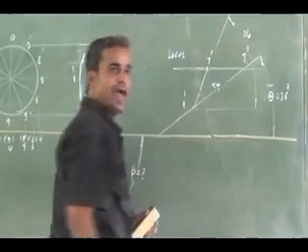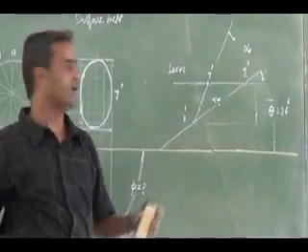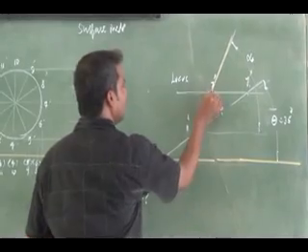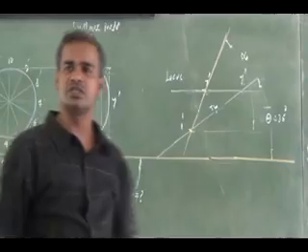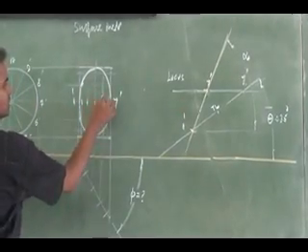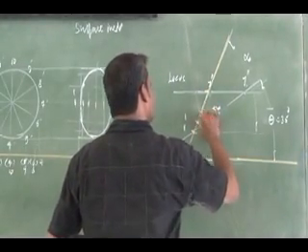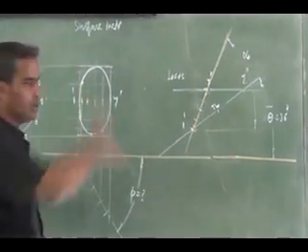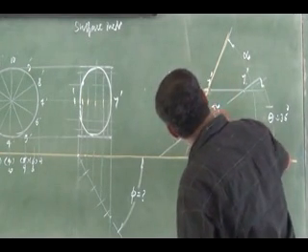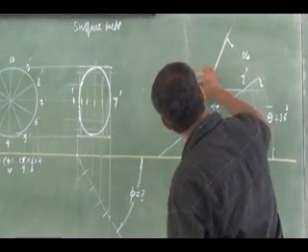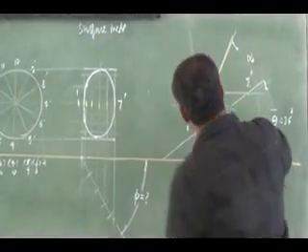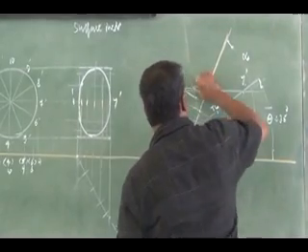So I have got a line for the alpha angle, which is not given, that you have got from this. Along this alpha inclined line, I have to reproduce this front view. As in the previous problem with the circular lamina, along 1/7 you mark the projector locations. That projector location you transfer, drawing perpendicular projectors. Then I can measure these distances and transfer them. So that is going to be my final front view.